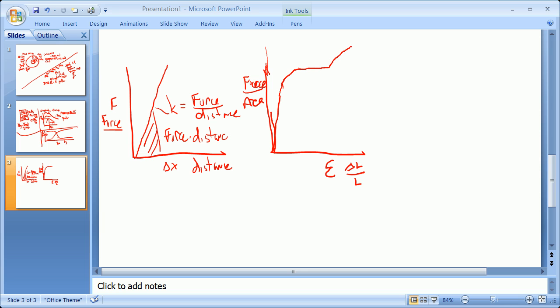Something stretches, and then eventually you go to a point of ultimate failure, where in this case we have what's called the yield stress here and the ultimate stress there. Yield strength or ultimate strength, yield stress or ultimate stress, and that has units of force over area. This curve, what is most important about the stress-strain curve, besides the fact that you can solve it out for a formula that please do not forget, is that the modulus of elasticity, or Young's modulus here, has units of stress.